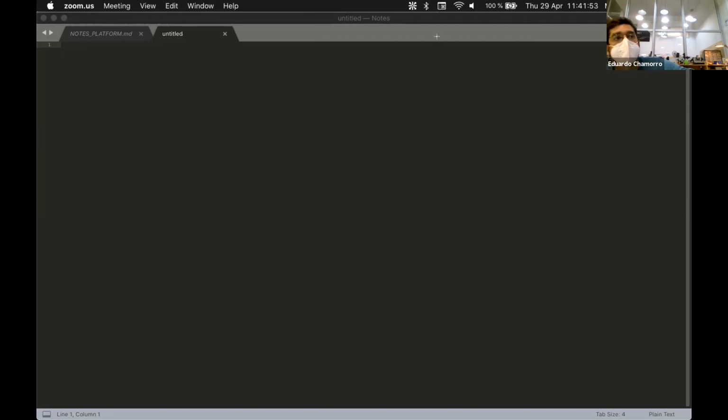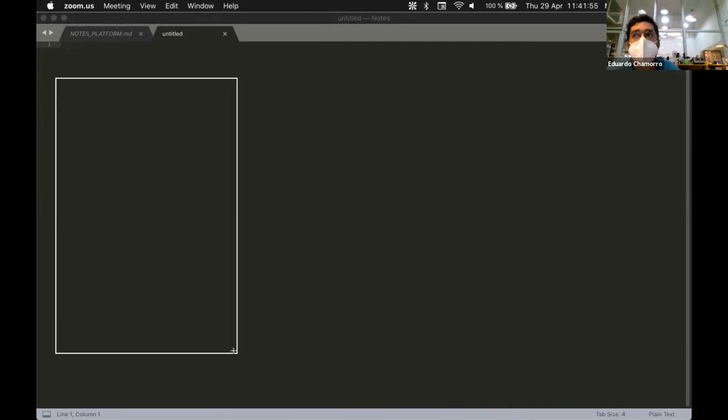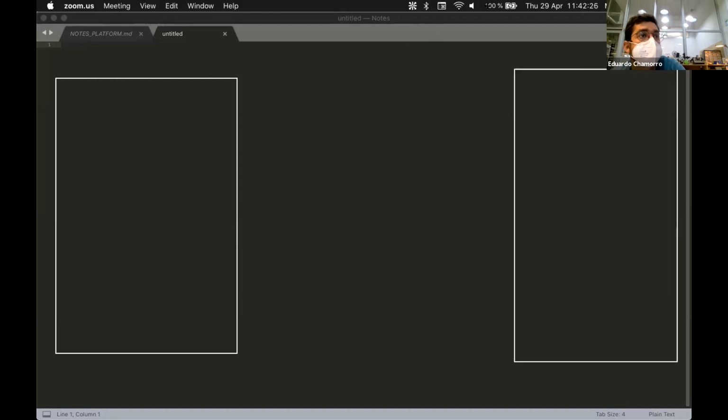Can we use voltage dividers as level shifter? No. A voltage divider doesn't amplify. No, the opposite. To reduce. If you're working from 5 to 3. Yeah, but then the communication in I2C will always happen in both directions. Sorry. Since you only have a data line, you could have a voltage divider on the clock line. I have never seen that. It's a silly question, but no.